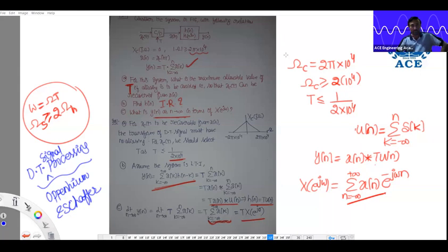You have a confusion in the second point, sir. What is the confusion? Find the impulse response is the question. Already the output expression is given. Listen carefully. We clearly know output is the convolution of input and system, xn convolved hn. Just recollect the discrete convolution formula sigma xk h of n minus k. This expression is given as what for us? T into sigma xk.